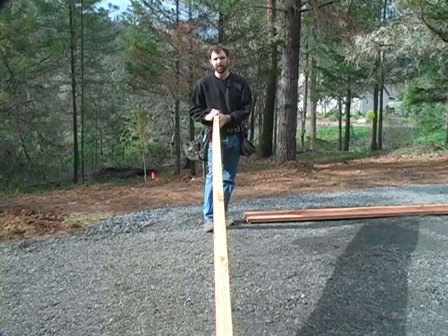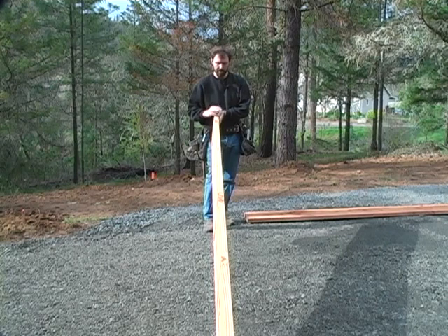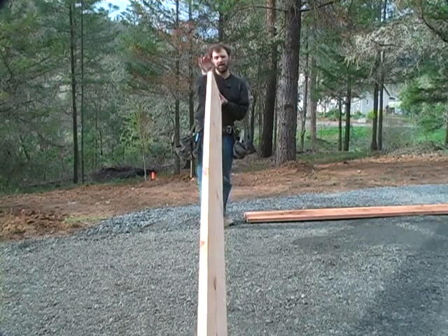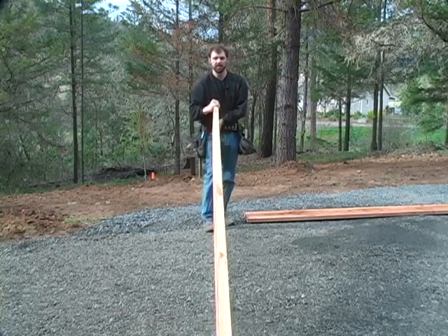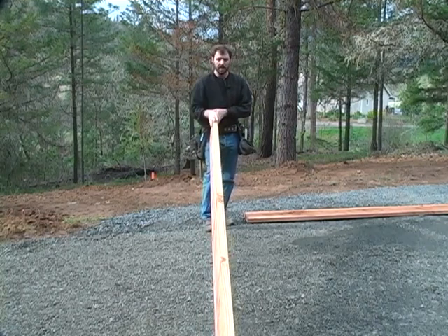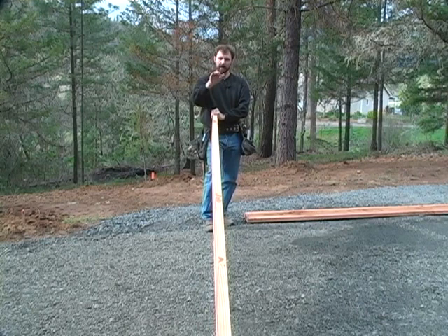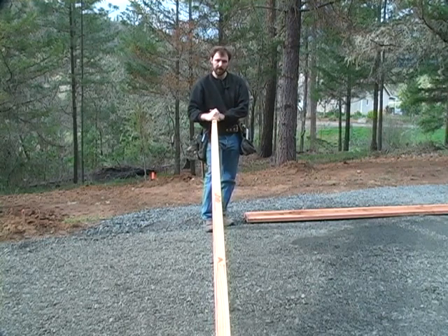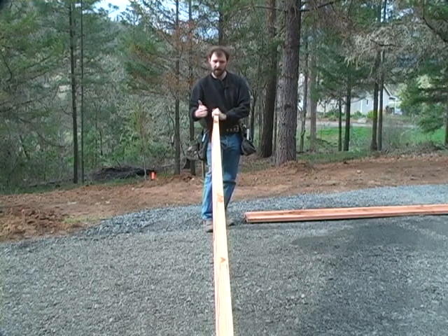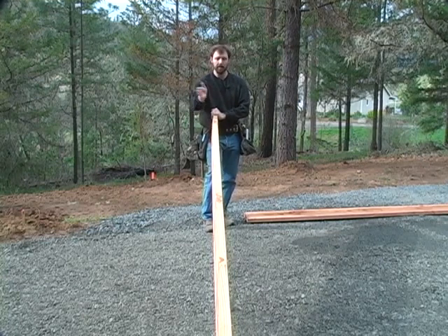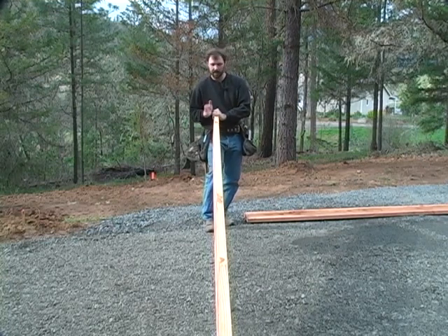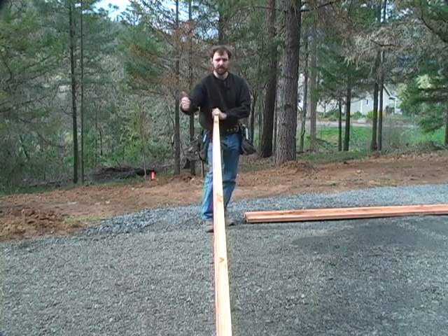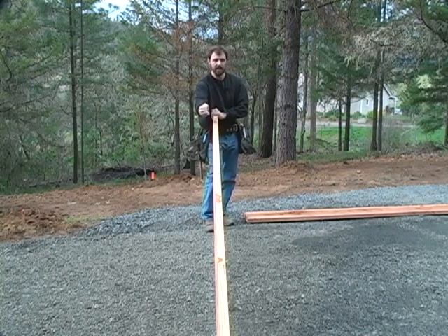When you're setting up the forms, you want to sight down the edge of the form to look for crown. This direction coming up or down is crown, and also some sway from side to side this way. If you have crown, you want to crown it up so that you're not creating holes in the middle of your slab. If you have some sway, you want it to sway out to the end or bow out to the outside. I'm exaggerating that in this case like this, because then we can adjust it and push it back in and stake it in place.